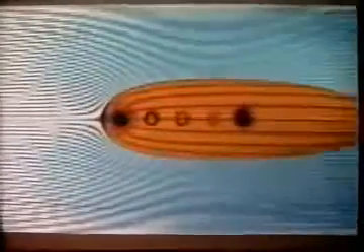Now, instead of a solid body, a source is started in the flow. Here is the flow round a half body. The red dye shows the internal streamlines. When the rate of fluid flowing from the source is constant, the streamlines are sharp. But when the flow from the source changes, the lines of colour become blurred because the faster particles, midway between the top and bottom plate, no longer find themselves close to the lines of slower particles which started earlier from the same neighbourhood.